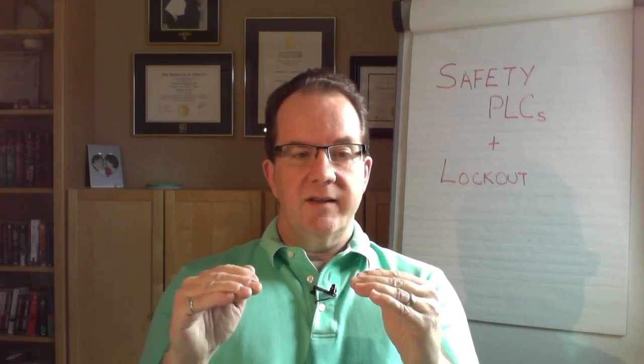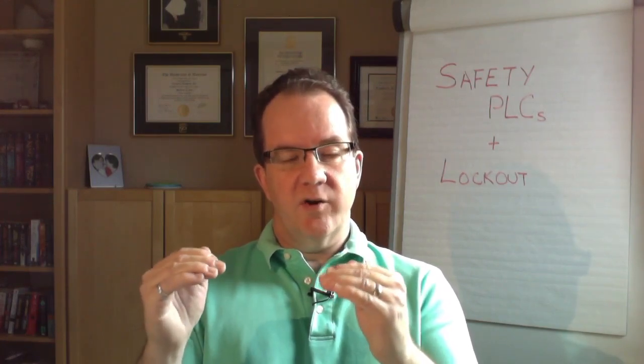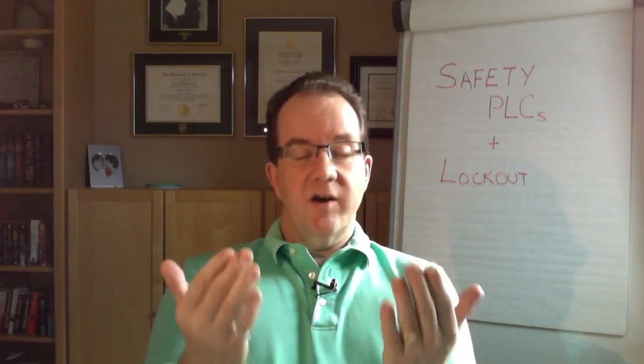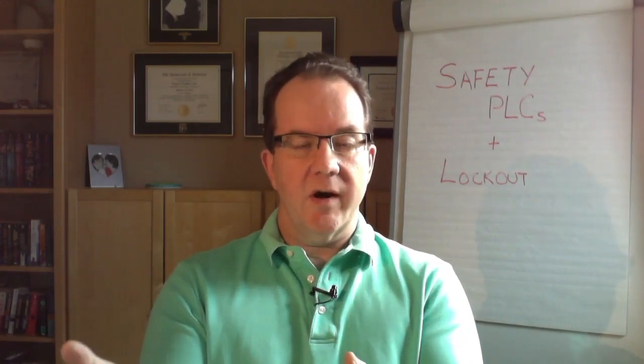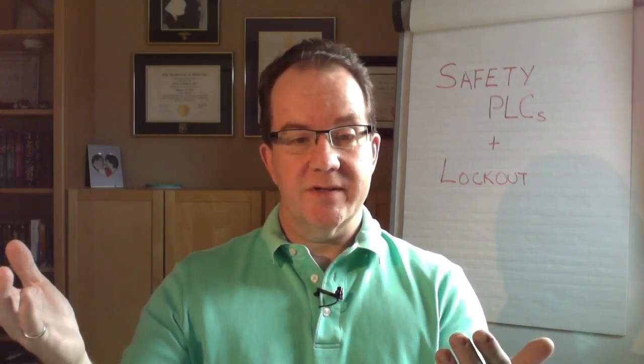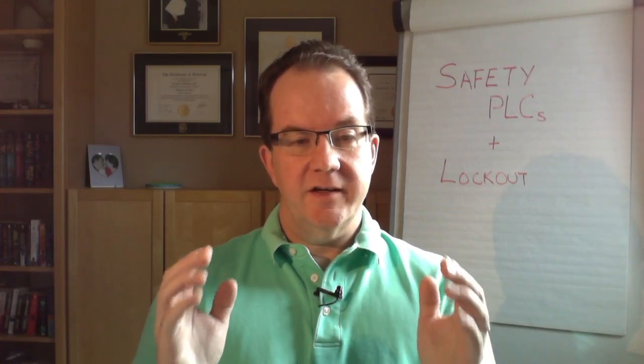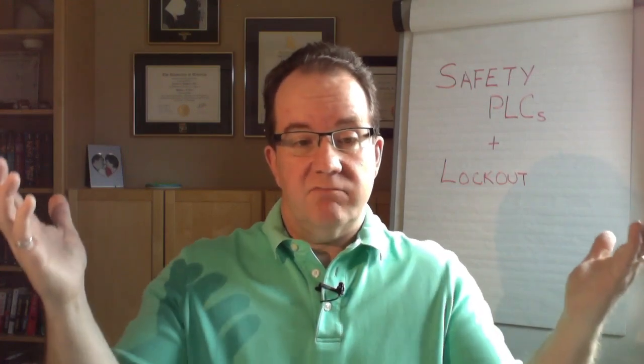Okay, category 3 and category 4 both require that they are single fault tolerant. So what that means is the system will continue to operate normally with a single fault, but you're relying on the diagnostics to determine whether there are any other faults. And so in category 3, because the diagnostic capability is only 60%, and in performance level E, we're talking 99%, there's still a significant population of undetected dangerous faults that may exist that you can't tell if they're there.